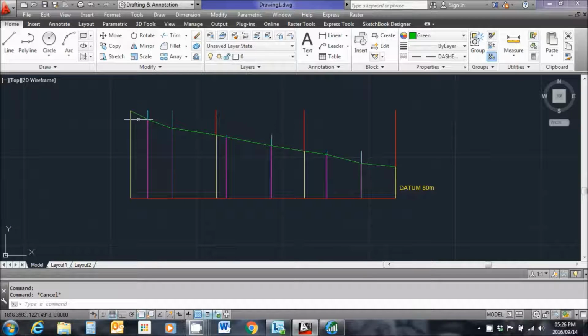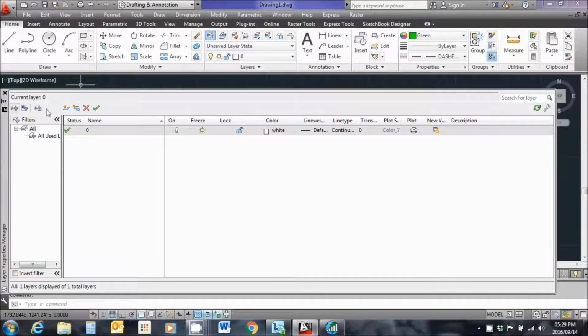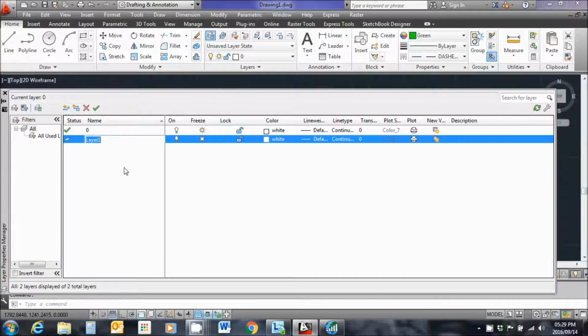So what I've effectively drawn in now is the ground line, and this is where we can have a quick pause. Okay, having drawn in the ground line, there's now an opportunity for us to tidy up our drawing a little bit. So I'm going to switch on, create some layers. I'm going to create some new layers, and one of the layers I'm going to label is construction lines. And I'm going to set these not to print, and I'm going to make good.